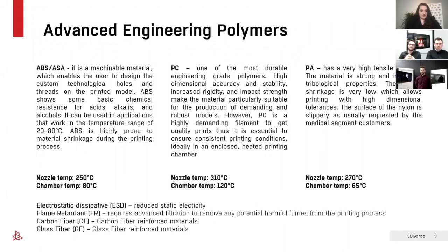Okay, polycarbonate, a very different material, excellent for impact properties, but also demanding when it comes to good processing. Again, a lot of different grades exist. There is a characteristic of the material that is called glass transition temperature. And without getting into too much detail, you could say that this is a temperature at which the material loses its ability to exert a deformative force and basically build up internal stress.